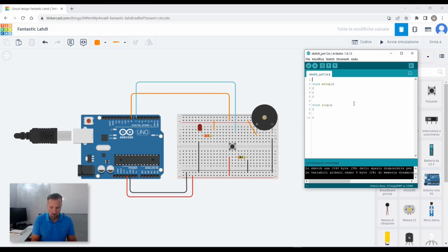As for the code, first of all, I would use define to declare. So define 8 as output. We call it output, pin 8, which is the one that powers the devices. Let's call the button number 7, which is the pin we will read to understand the button state. So in the setup, the only thing we will put is the pinMode, to define that pin 8 is used as output, while the button, pin 7, is obviously an input.